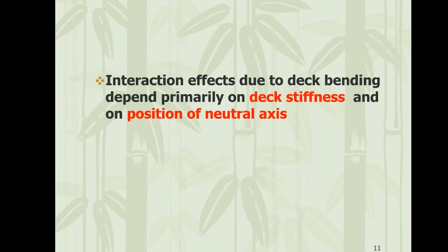What do you mean by deck stiffness? What is the meaning of deck stiffness? Section modulus of... Yeah, basically deck stiffness will be given by your EI value. Right? Now your deflection is inversely proportional to EI.